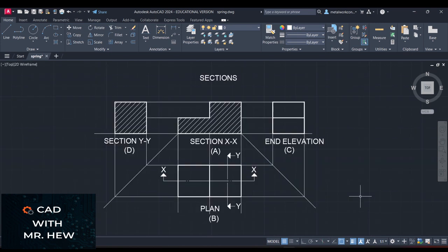So you recall that the section XX drawing, which is this drawing up here, right, was a sectional front elevation. So that is why it is right here, right? Now the plan was a section, so it will maintain the same place here. And the end elevation looking from C was not sectioned for today's drawing, so it will remain in the same position.